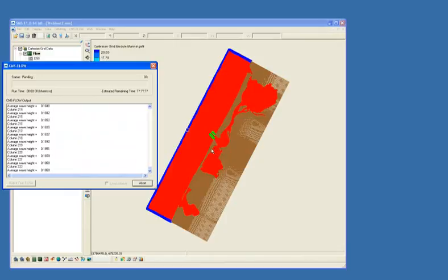So what this is going to do while it's actually doing it, we've specified a number of wave conditions, and it's taking the first one, which is what it just ran there, and it's now calculating an extrapolation distance automatically. And that's because CMS is doing all the mapping from the flow to the wave grid itself.